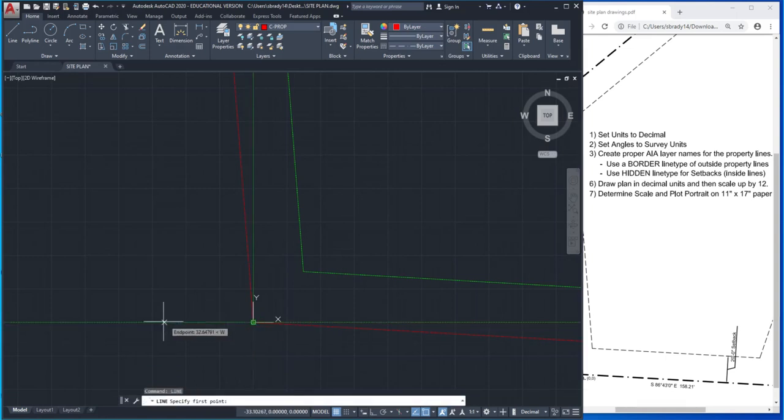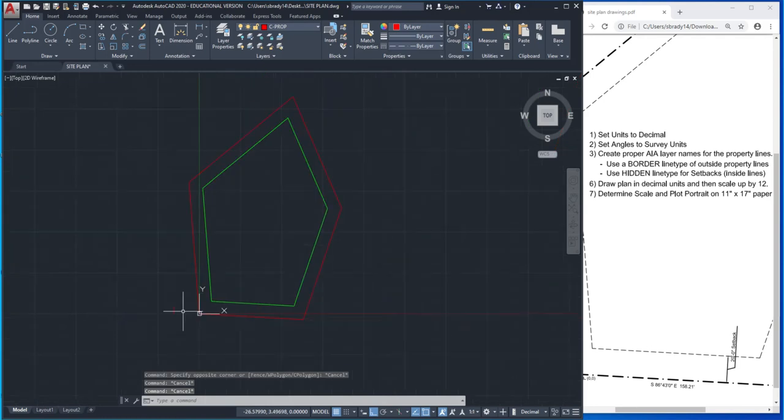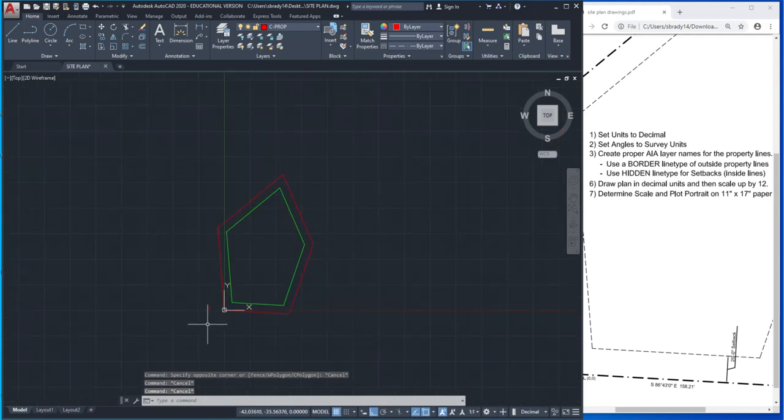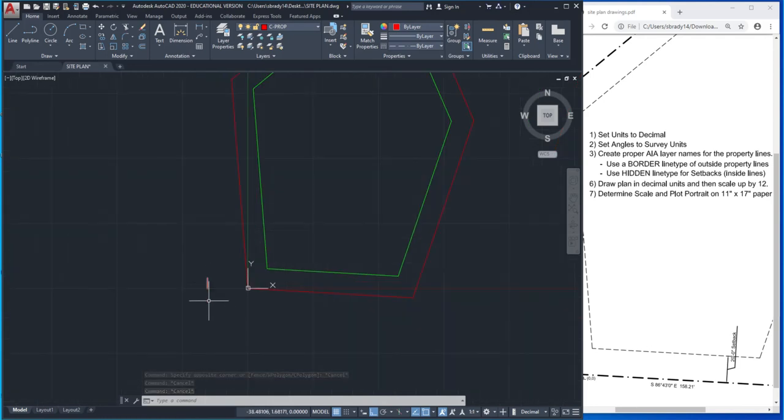Sometimes I will just draw a little piece of line that I know the length of, maybe we'll just type in 10, enter, okay? And it's tiny. So I can type distance and I can measure it and it says 10. Now, if I scale up this site plan, and I select this at the same time, that line will scale as well. So if I measure it and it's larger than 10, I know I've scaled my object, okay?